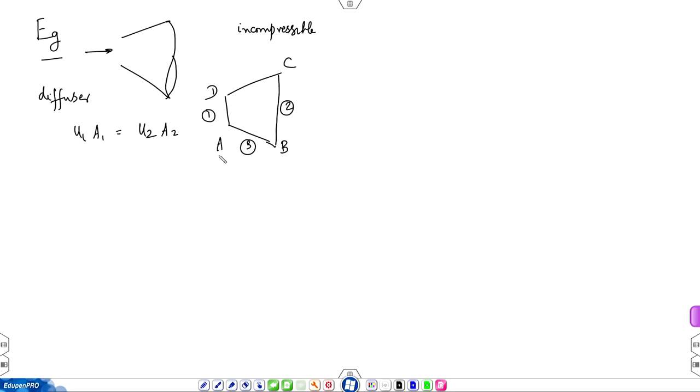So, sometimes called the no slip condition. So, in the tangential direction, we often use a no slip condition. That is, the fluid sticks to the solid surface. If the solid surface is stationary, fluid is also stationary at the wall, but it is moving inside, which means a velocity has a distribution inside the tube.